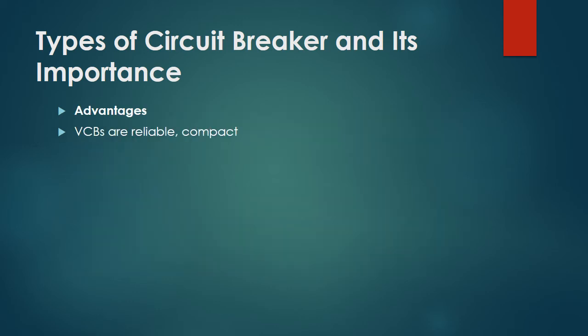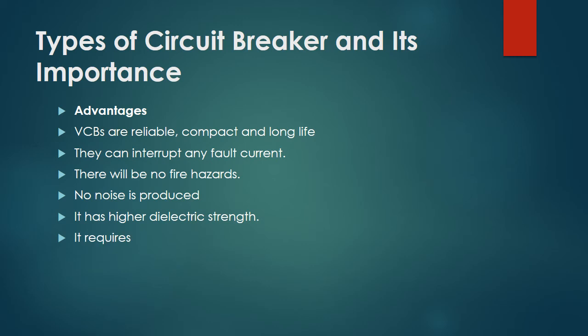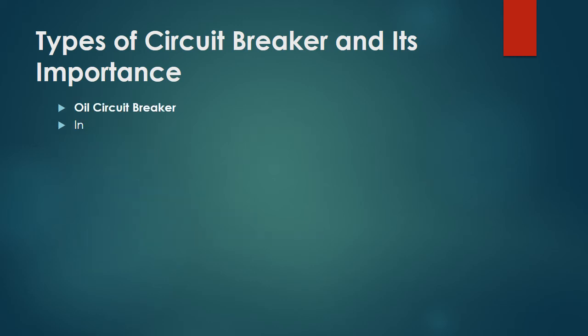Bulk Oil Circuit Breaker, BOCB. In the BOCB, oil is used as the arc quenching media and also as insulating media between earth parts of the circuit breaker and current carrying contacts. The same transformer insulating oil is used. The working principle of the BOCB says that when the current carrying contacts in the oil are separated, an arc is generated between the separated contacts.